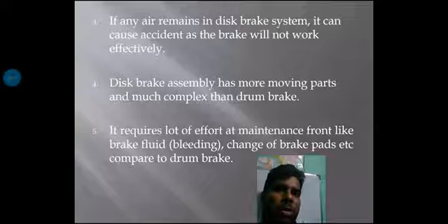If I use the uniform pressure theory, we can write R_f is equal to one third of (D cube minus d cube) divided by (D square minus d square).